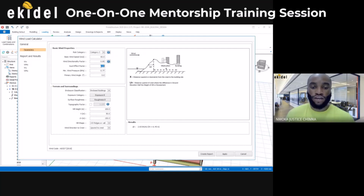Then also for the gust factor and all that, the gust factor value ranges from 0.5 to 1.0. For me, I can choose 0.85 because this is a factor that will add to the wind pressure.